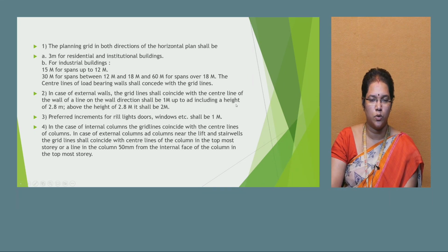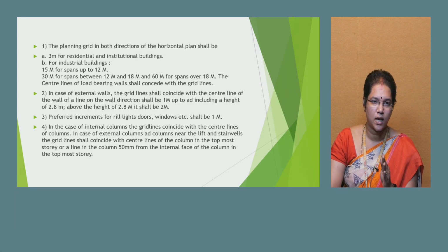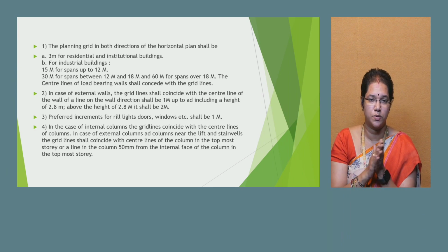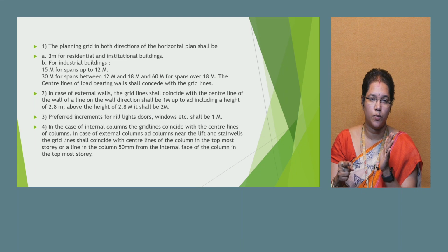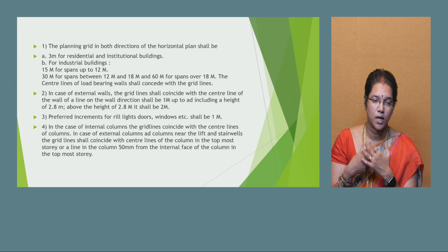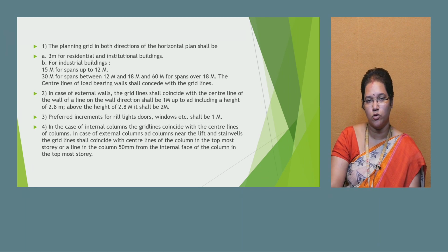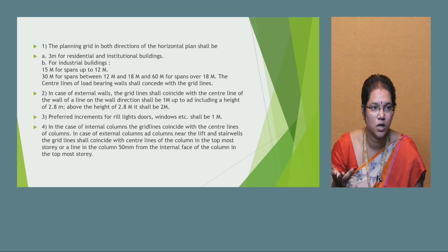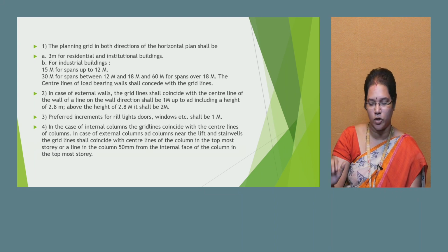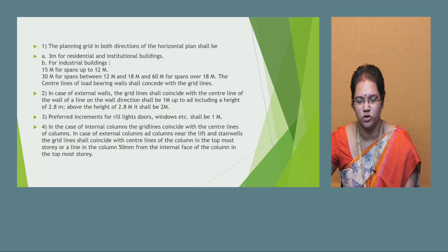1M means one module, we call it. We will ask in such a manner that I need one module, 1M, I need 3M, I need 2M, likewise. It will be with reference to height and dimensions. When we are going for 1M and the standard, what is the dimension? 2M, what is the dimension? For the column, what will be the interface connection? So 50 mm is the interface of the column, and likewise this will be there. This is an easy way of asking. Only technically skilled persons will understand this. Other people will not be able to understand what is 1M, 2M; they won't understand. So this is a very common prefabrication language. Next is another interesting topic we'll deal with. Thank you.